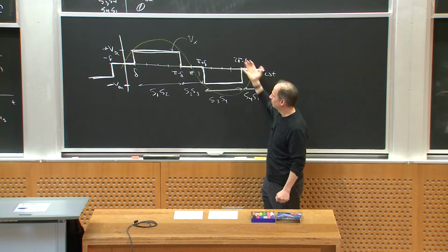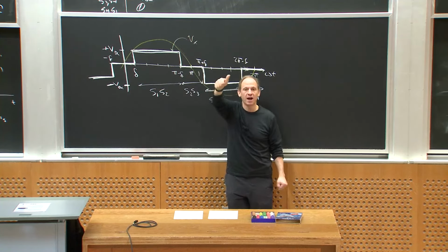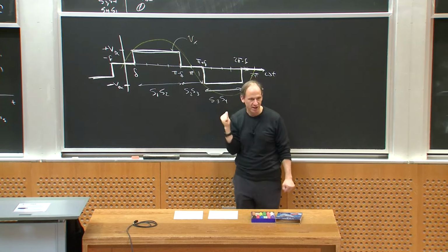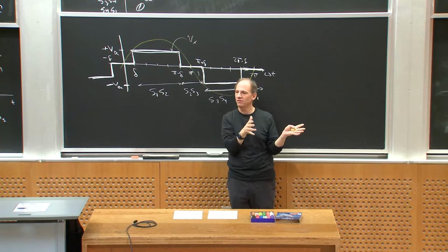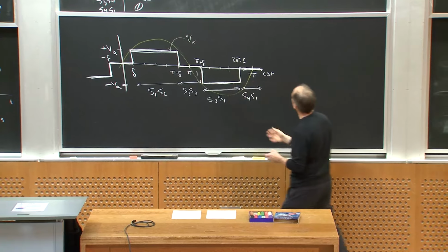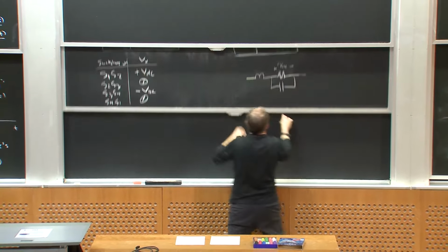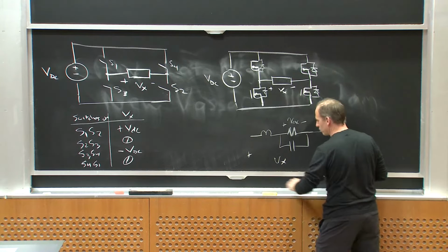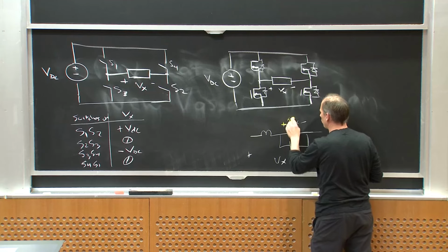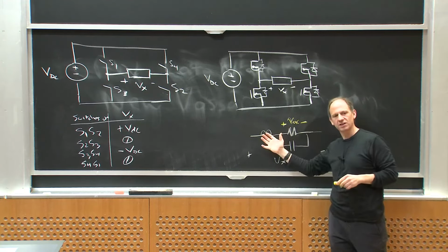So the reason I chose this pattern just this way, for both being odd, because I happened to be trying to match a sine wave, but more importantly that I made it half-wave symmetric, is that I've gotten rid of even harmonic components. And if I imagine that I was going to take this Vx here and try to synthesize some output voltage VAC by filtering it, if I can get rid of my even harmonics, I can more easily filter that waveform, right?